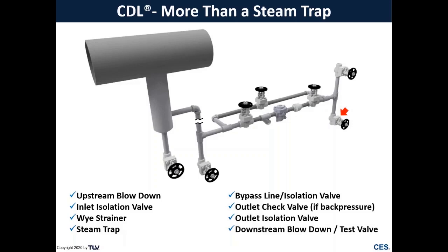Now you may see all or some of these components at each one of your CDLs depending on what type of application you're draining, what pressure, and what your site specifications are. But it's important that whenever we're inspecting a steam trap that we actually take a step back and look at the entire CDL and see if there's any problems associated with any of these components on the CDL.